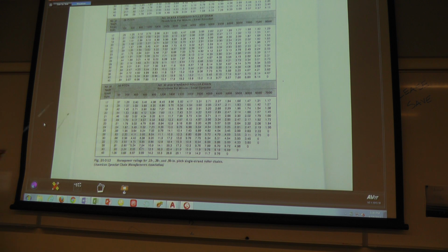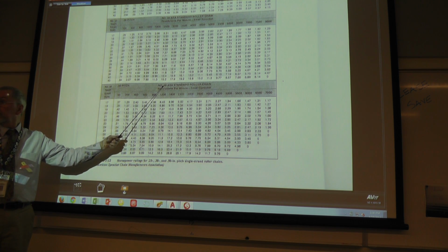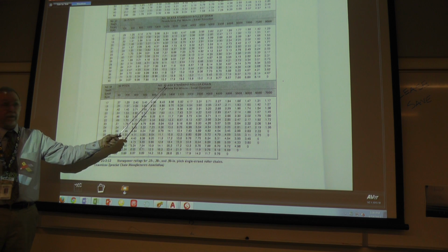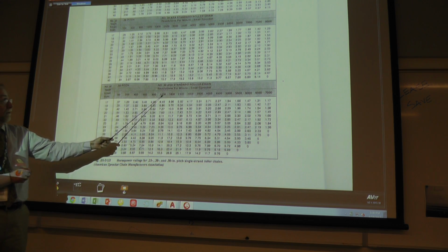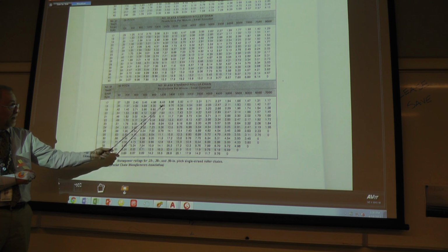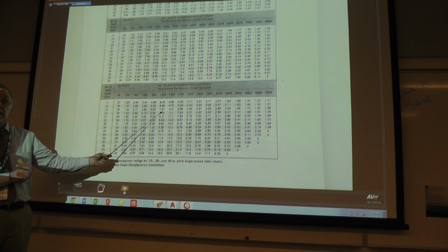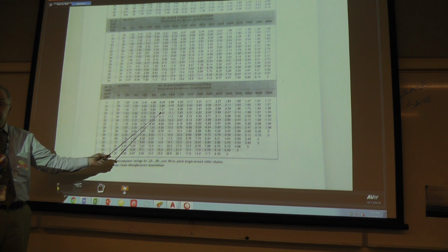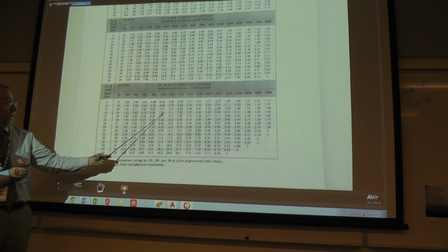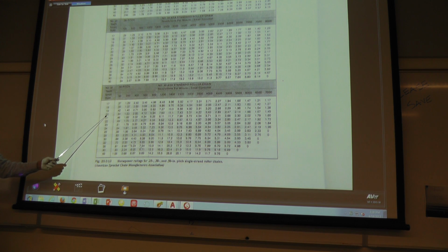All right. So I got the 40 from that horsepower chart, fell in that band. So I go back to the number 40. Then I look for the RPM of the small sprocket, which happens to be on the motor, and I come down here until I find the closest number to 7.5, which is my revised horsepower due to the service factor. 7.69, I come across here and I see that there are 20 teeth on the small sprocket.